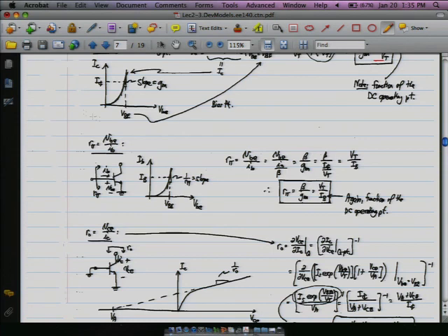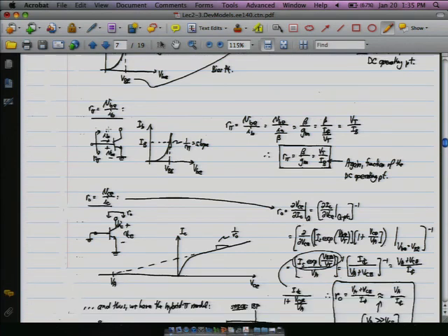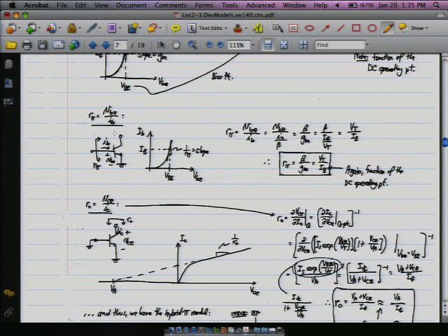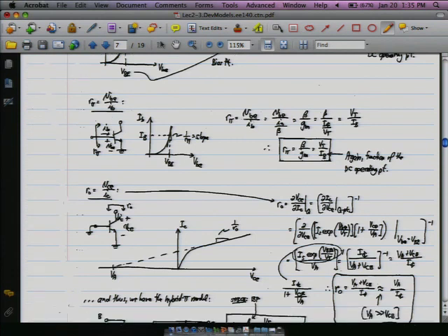So then to pull out the R pi value, again, basically, it's the ratio of the voltage at the base to the current in the base. And so we go through the math. This time we can say that we express the base current as the collector current over beta, because that was basically from how we defined beta earlier.